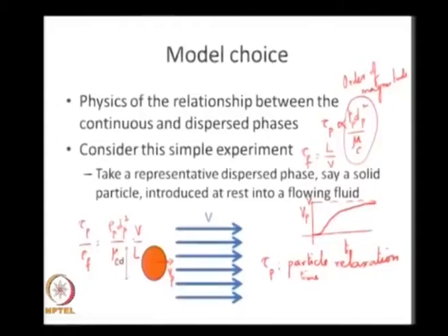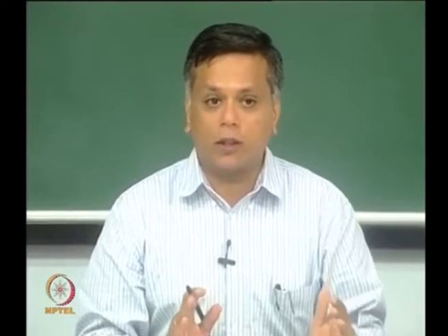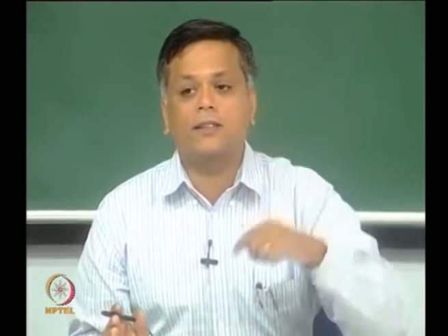phase model, but understand that I need dp, V and L. Rho p, I am assuming you know the material properties of your phases, but you also need an approximate size of the particle you are expecting. You also need an approximate size of your domain, which you may know more easily than dp. And you also need some estimate of the residence time, which is L over V.